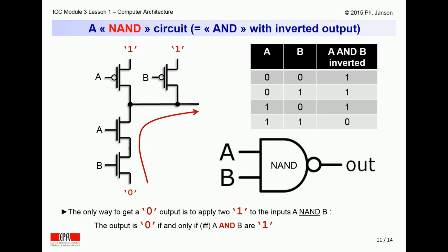It is also exactly what the transistor implementation yields when one applies logic 1s and 0s to its inputs A and B. For the output to be 0, both of the lower NMOS transistors must be closed to connect the ground to the output, while both of the upper PMOS transistors must be open to avoid short-circuiting the power source. This is indeed the case when A and B are powered to a logic 1.